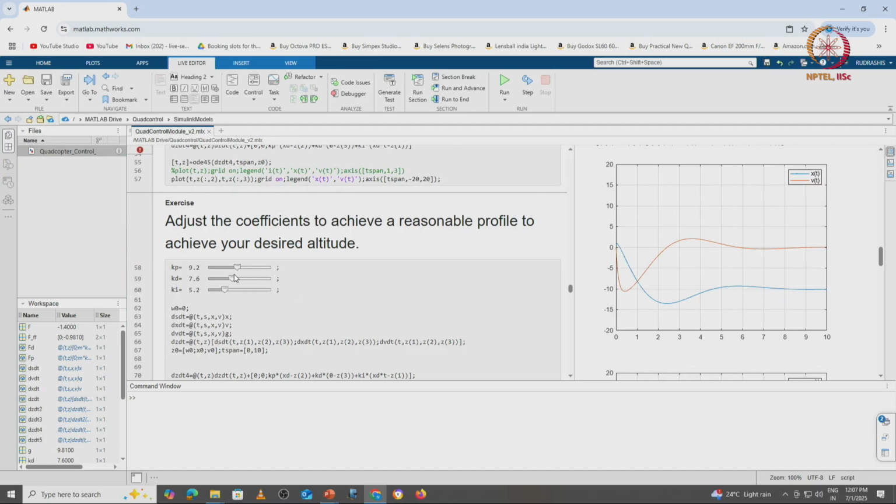So how do we do that? What we do is we take an open loop response for a step input. We can use a reaction curve method, or we can find out the critical gain. From the critical gain we can find out what the integral and derivative values should be. Based on those values as nominal values, we can go into the simulation and see what values of Kp, Ki, Kd achieve my desired performance.